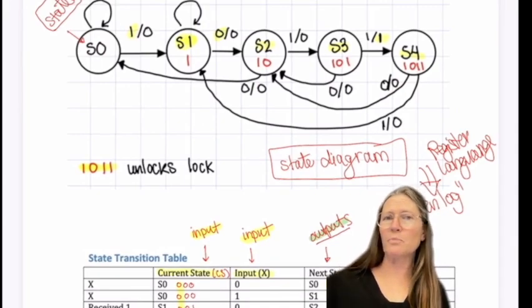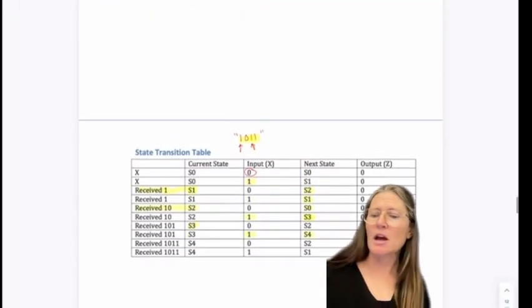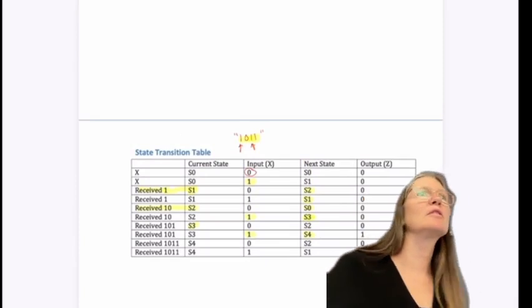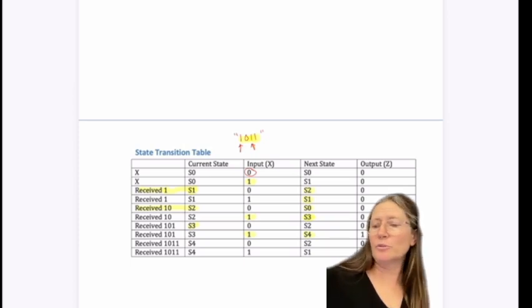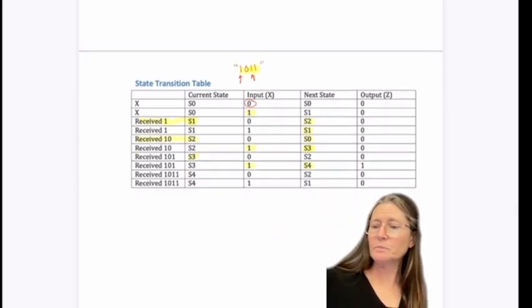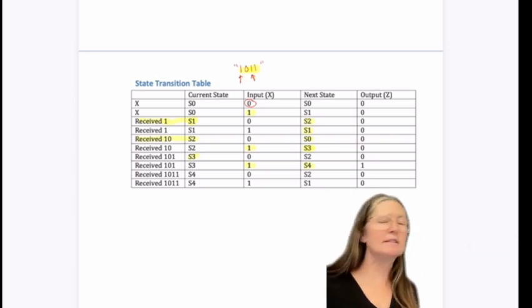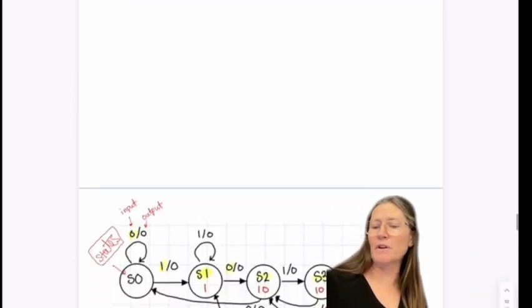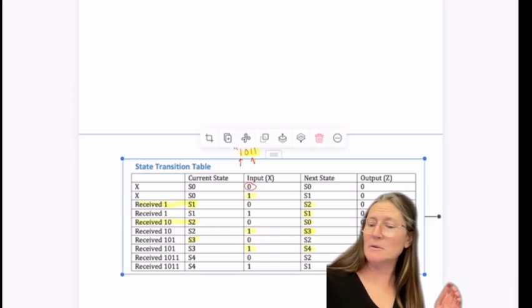I could say, for this type of system, how many states would you need, and to clarify what those states would be. In this one, you would need 3 states, if you had 0 in there, which was really 4 states. So you would have 4 states, and then you would need 3 flip-flops to encode that many different states. Does that make sense? So that could be a question that I could ask.